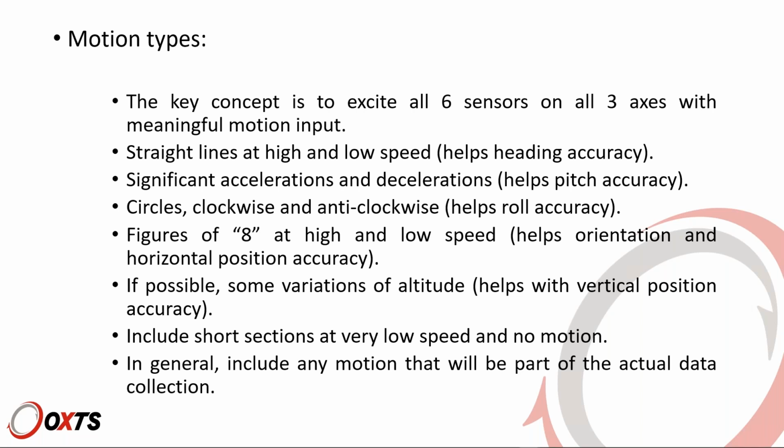If you know that you are going to be traveling slow all the time, there is no point in pushing the speed during the warm-up to say 100 miles per hour, because you are never going to reach that speed, so there is no point. On the other hand, if you know that you will reach, say, 60, 70, 80 miles per hour, then make sure that that's included in the warm-up. Do not do a warm-up at 15 miles per hour and then do data collection at 60.